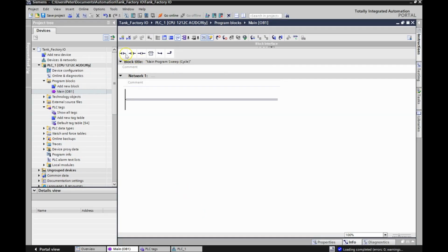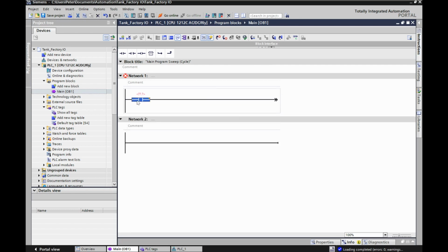Let's drop these guys in. We're going to grab our stop push button, and we want to make sure that the stop is still closed. As long as it is closed, then there's voltage going to the PLC. That means that it's still in its rest state. Okay, we've already done our